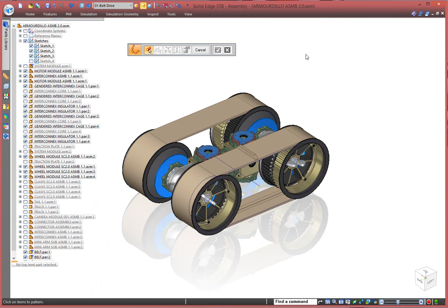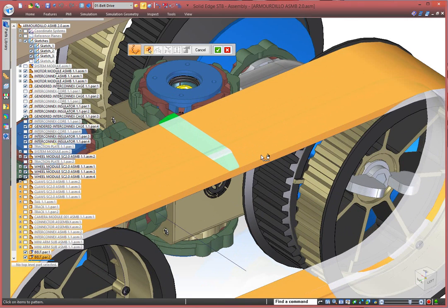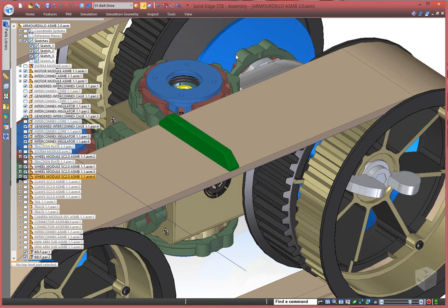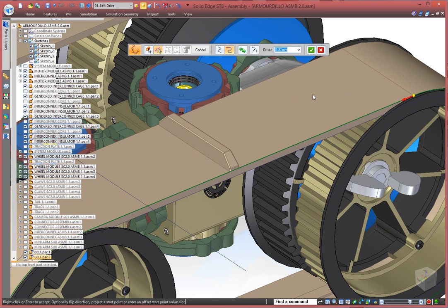In order for us to replicate the tread around the belt, we can use the pattern along a curve. Obviously this command offers several options to help you achieve the pattern you are looking for, but a new option within the command in ST8 is the ability to create a chord length pattern, which gives you the correct results when tracking a squared edge part around a curve without having to create any awkward construction geometry.